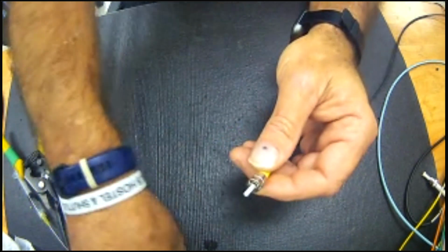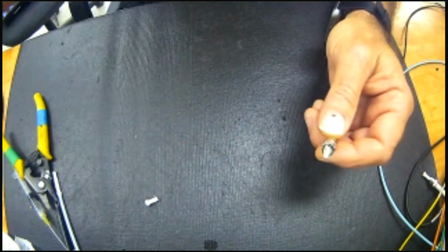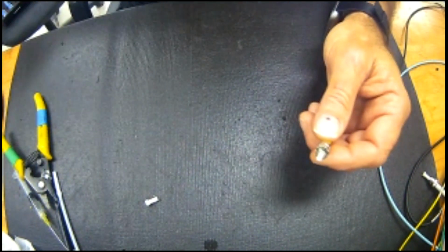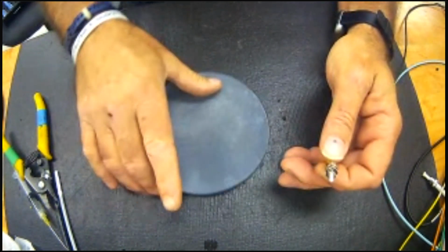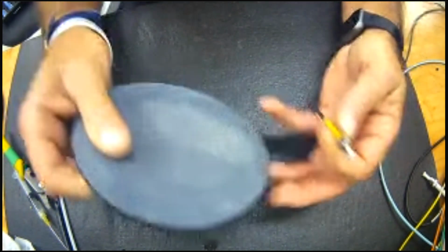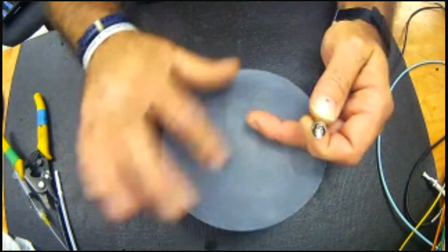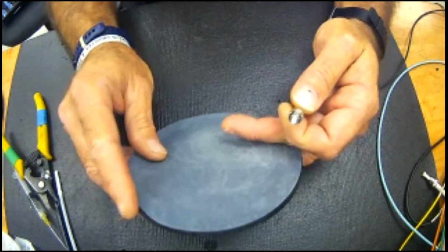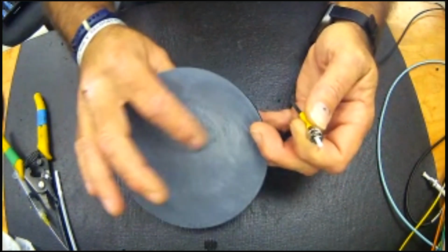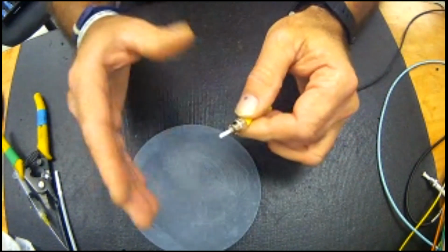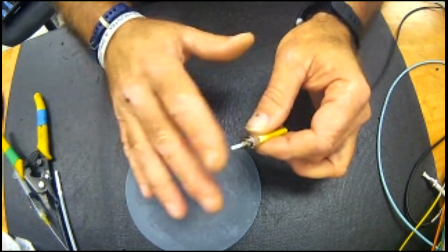Now, you can either invest in a large bench mount polisher, or I'm going to show you a basic polishing technique by hand. I can do this, and I still do this regularly. These are pads from my base polisher. They're 90 durometer. The film that's on here is 15 micron silicon carbide. Basically, it's a dry film. And as you can see from the scoring on it, it is used just to reduce the epoxy that normally appears on the tip of the connector and the glass.